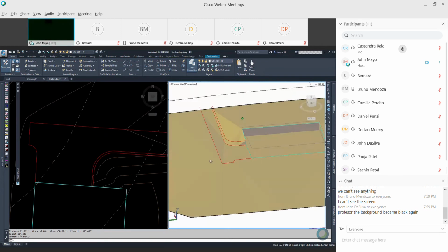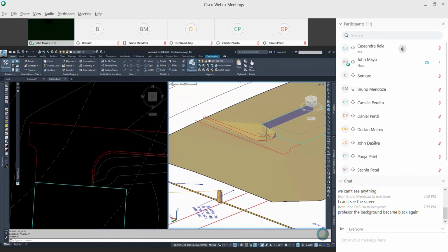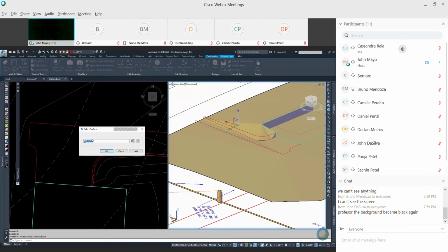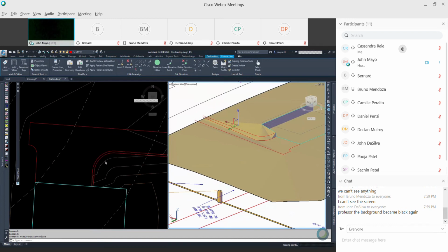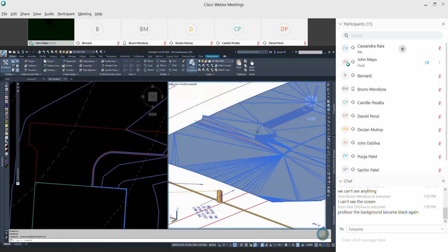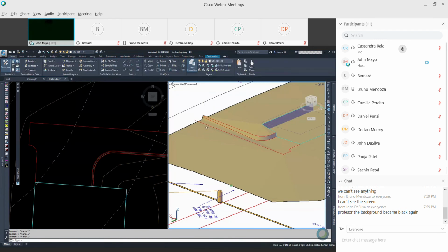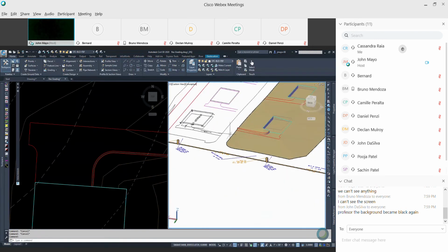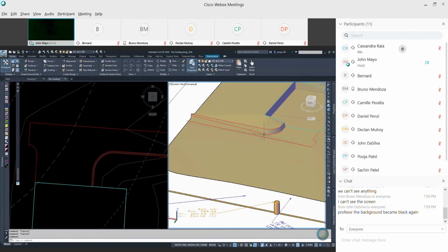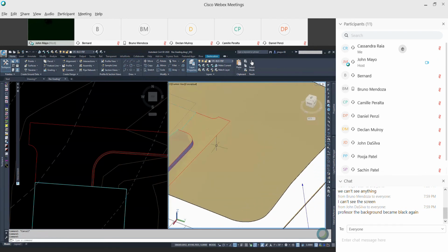But if you notice, my wall, the top of wall is not in that surface. Let's add that. Press 2, that's the right surface. I hit OK. Now we see my top of wall going in there. All right, so I still have a few more issues. Number 1, I do want to level my driveway over here. And number 2, I'm not hitting existing grade.